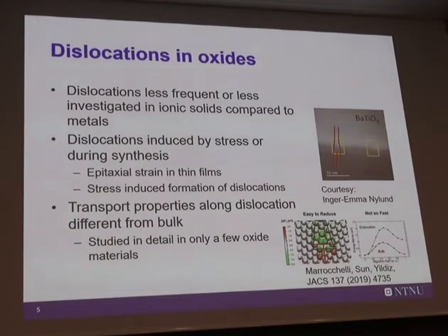For example, it is easy to reduce transition metal ions sitting on the edge dislocation, but it's not so fast. It means that in some way ions or defects are kind of pinned to the dislocation. Many have predicted that the dislocation would represent a path where ions move faster, but it has actually been shown to be slower. So this is a topic now studied quite a lot all over the world, but I will not go back into more details on the properties of dislocations.